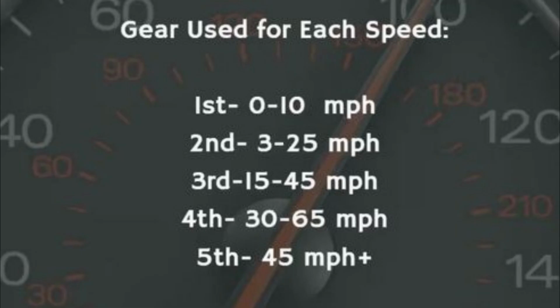Despite its advantages, the reverse gear has certain limitations. In vehicles without synchronized reverse gears, improper engagement can cause noise or wear. Reverse gear mechanisms also add to the complexity of the transmission system. However, these limitations are outweighed by the essential function reverse gears provide in vehicle operation. Automobile reverse driving gears play a vital role in enabling backward movement by reversing the direction of power transmission. Whether implemented through an idler gear in manual transmissions or through planetary gear systems in automatic transmissions, reverse gears ensure controlled, safe, and efficient vehicle maneuverability.